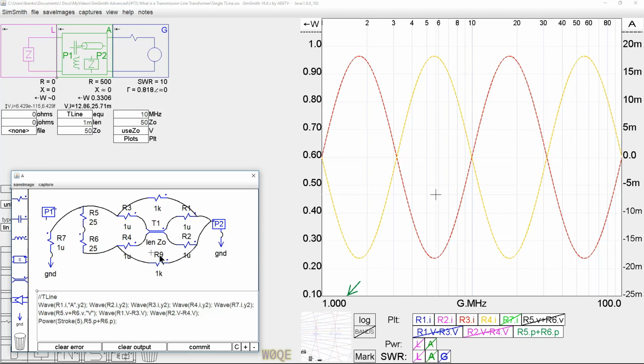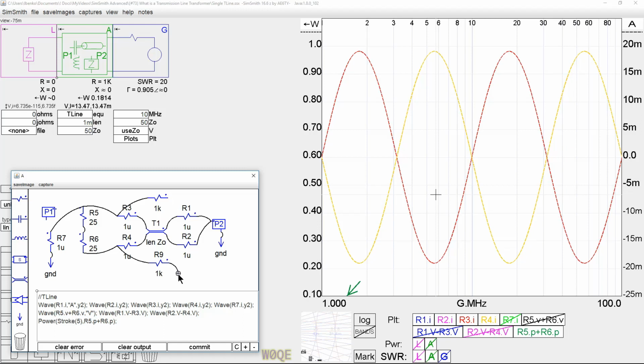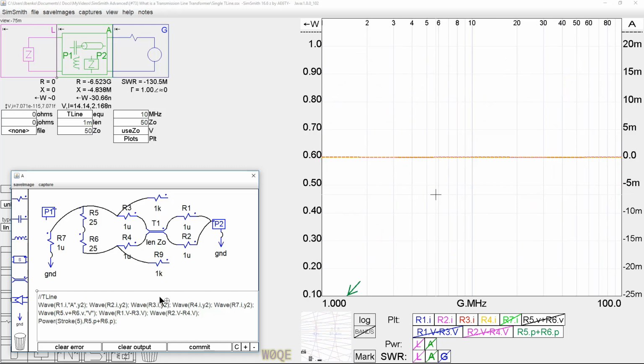So it is up to the user to put the impedance across the transmission line that represents the common mode impedance, if that's part of the circuit and if that's important. And it turns out it is important in transmission line transformers. But we're going to leave it out because it also makes the circuit more complicated and a little harder to understand. So we won't worry about it when we figure out how things work, and we'll worry about it whenever we want to actually build something, if that makes sense.